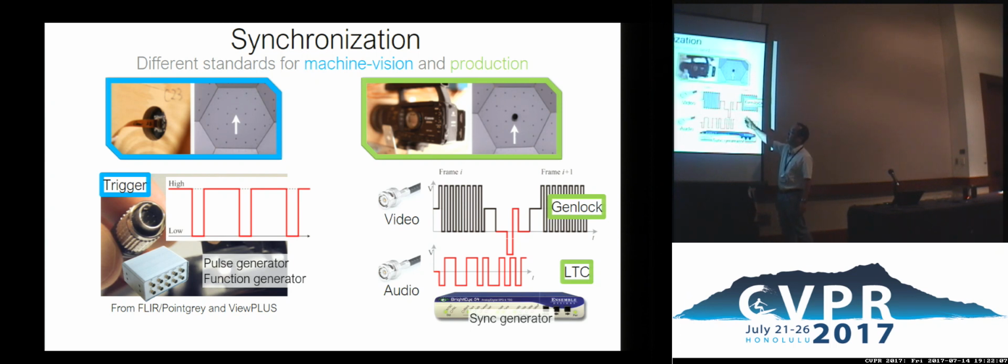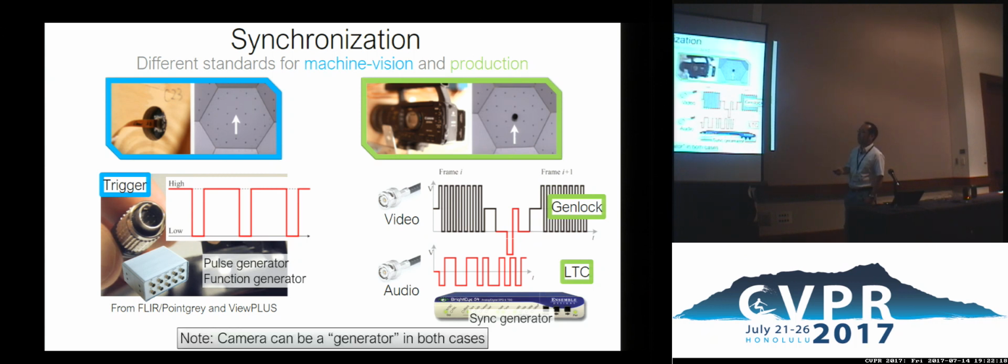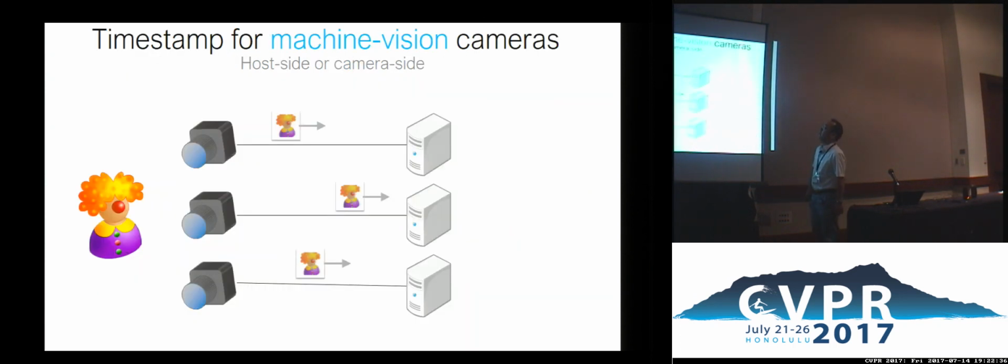So this kind of signals should be provided by sync generators. That means for these two subsystems, we should prepare two different signals just for synchronization. Of course, some of the cameras can be a master, and the others can be slaves. But anyway, we should distribute this kind of system over the studio. And in fact, in recent systems, we have a better solution.